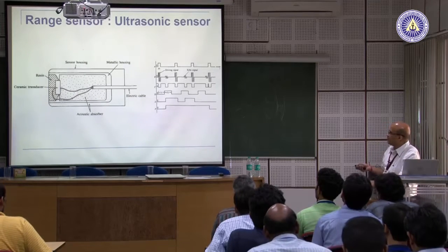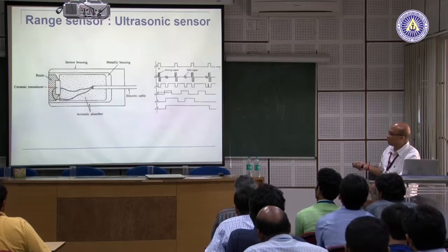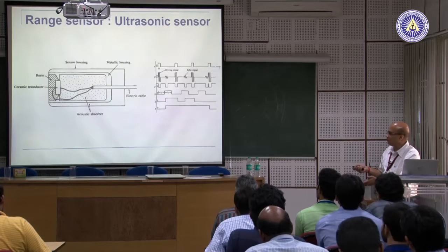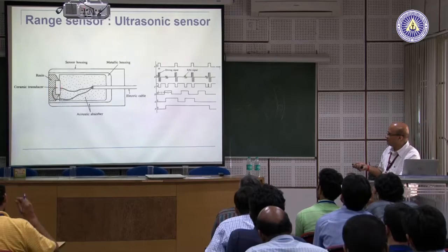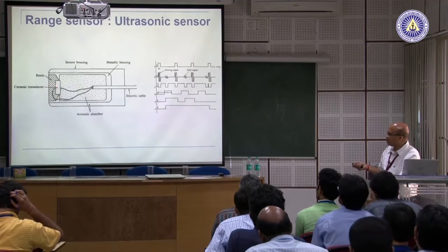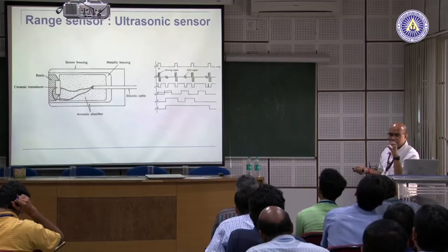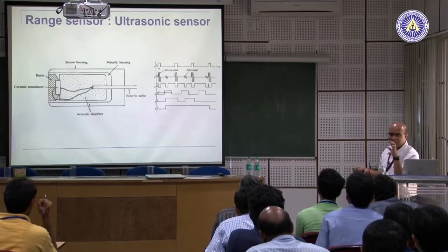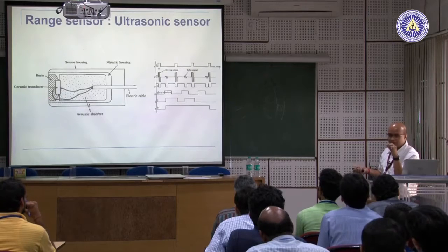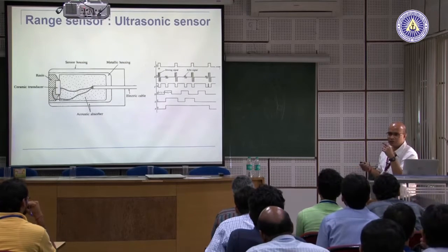The working is essentially based on the ceramic transducer or a piezo crystal, which is basically piezo. If you give it a charge, what will the piezo transducer do? A piezo crystal, if you give it a charge, it will expand, right? It will create a pressure. If you give it a pressure, it will create a charge. So, it works both ways.